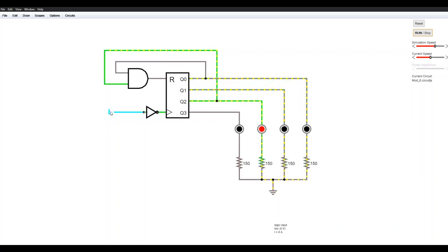So that's 3, 4. Then after 4 it becomes 5. And then this is now the output. The problem here is that whenever we use the 5 output, it directly resets your count. So this is your asynchronous counter. It doesn't wait for a clock pulse to reset.